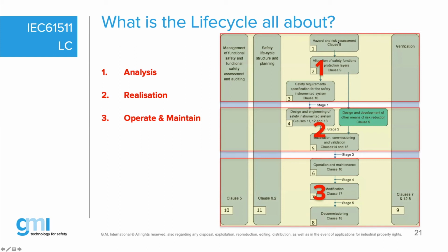That's where you do a lot of investigations, discussions, meetings, that you will have to agree with each other. What is the hazard? What is the likelihood? What are the consequences? Can we take some credit for existing layers, yes or no? If not, we're going to write a requirement specification, and that's all the analysis phase. That needs to be managed, needs to be planned, and of course needs to be verified. Every phase before you move on to the next phase needs to be verified.